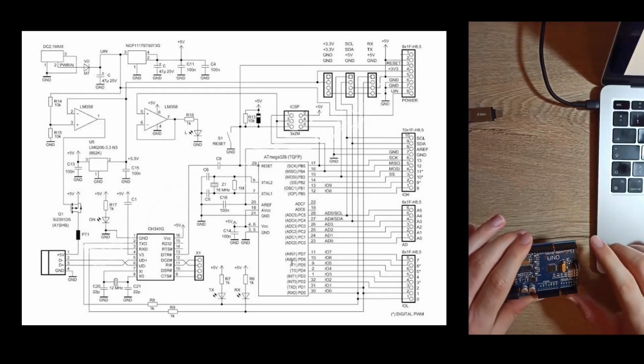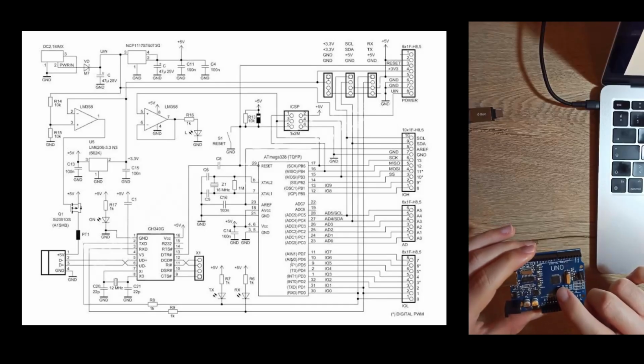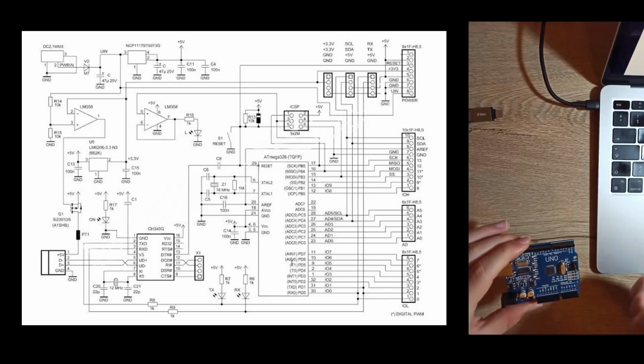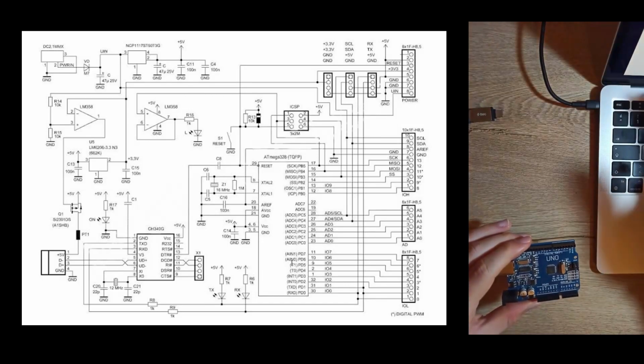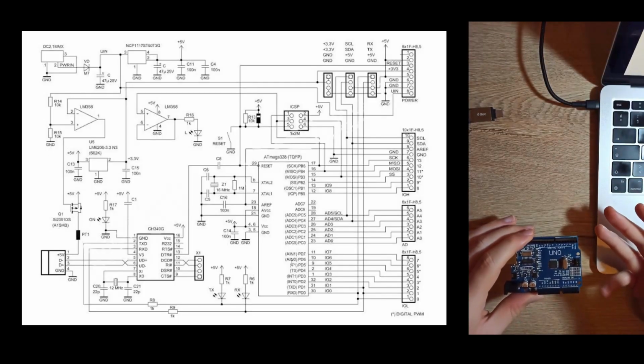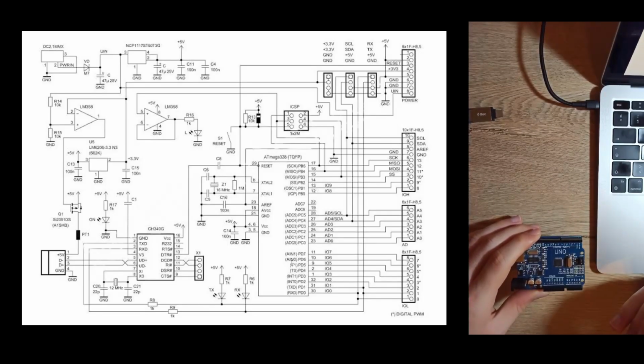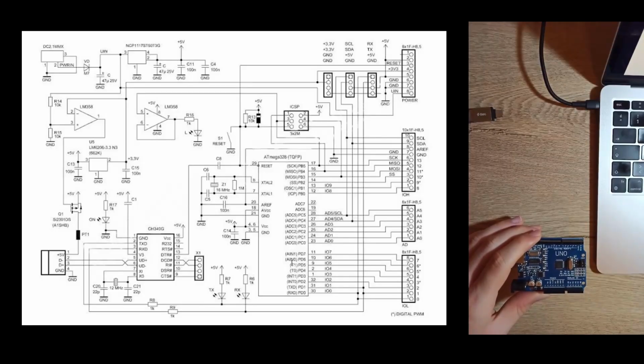So usually what Arduino Uno manufacturer does is they burn a bootloader program here that understands the UART data coming from the AVR tool from the computer, and with that protocol, AVR issues some commands and burns or writes the program I just wrote to the memory of the atmega chip.